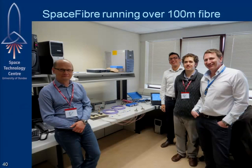Okay, and this is some tests we did at ESTEC. So this is ESA's Research and Technology Centre in Holland. And you can see here there's a couple of our Starfire units, and these are actually connected onto this board, which is containing some fibre optic transceivers. And then this purple bundle here is basically 100 meters of fibre optic cable. And that fibre optic cable has been designed for flight applications. So it's using a core that doesn't degrade significantly under radiation, and the sheath has been made to withstand a wide temperature range and all that sort of thing.